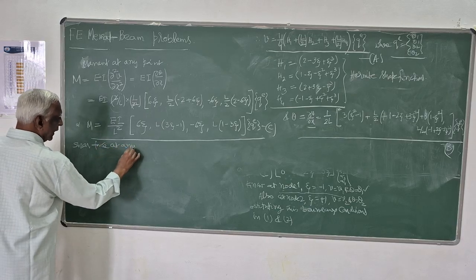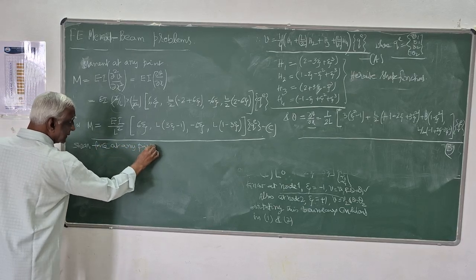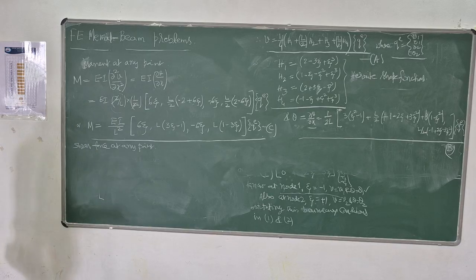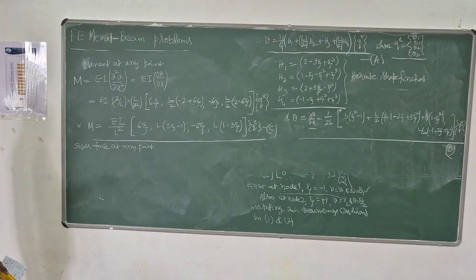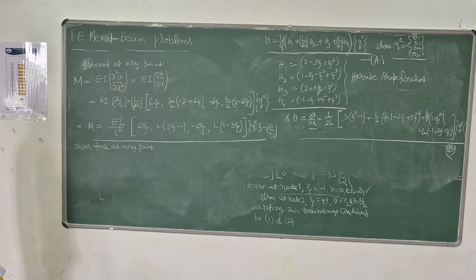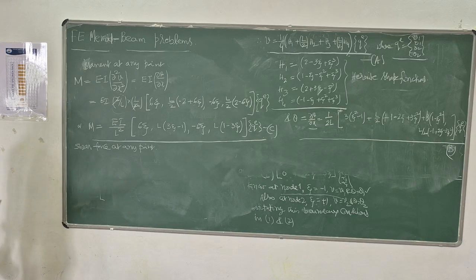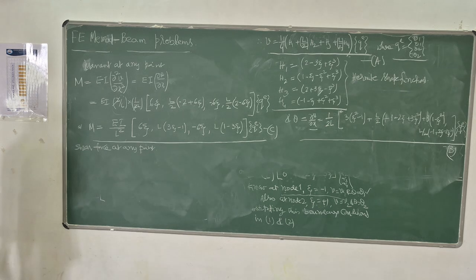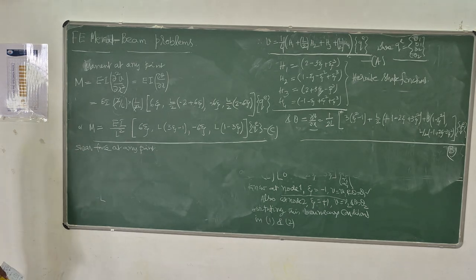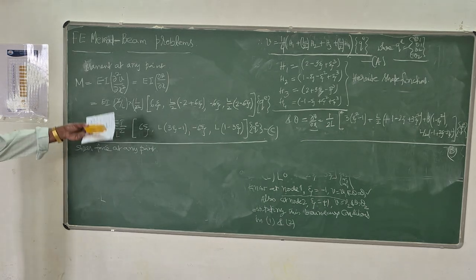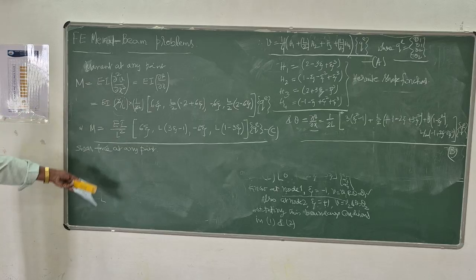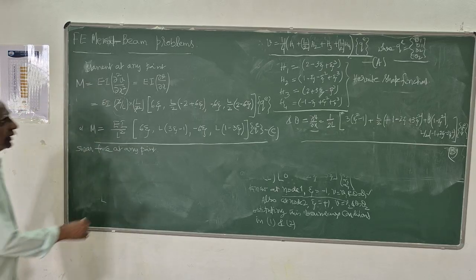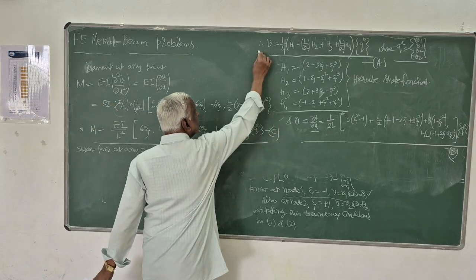And this is actually the difference between the finite element method and your conventional method of analysis, the other one we have done. Here, we are getting directly the equations for slope, moment, and shear force. So the only unknowns are these two, V and theta.